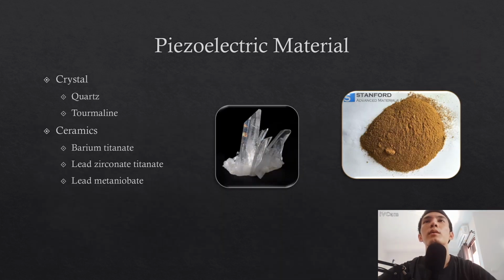Piezoelectric materials that are commonly used are crystals like quartz and tourmaline, and ceramics like barium titanate, lead zirconate titanate, and lead metaniobate. Crystals are more durable and can withstand higher temperatures, whereas ceramics offer more variety in the frequency range and price range.